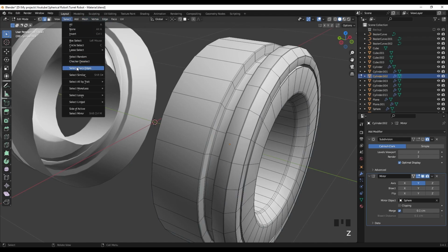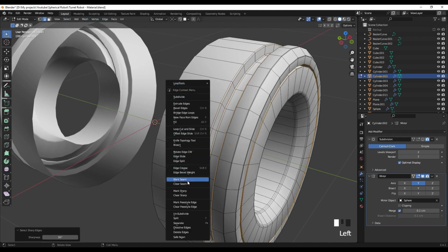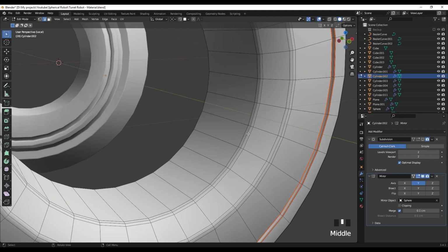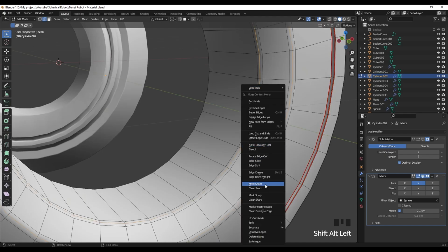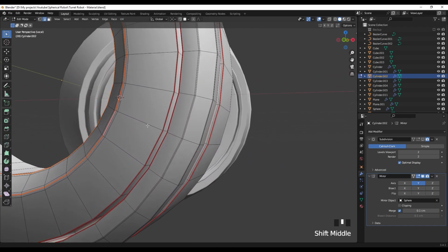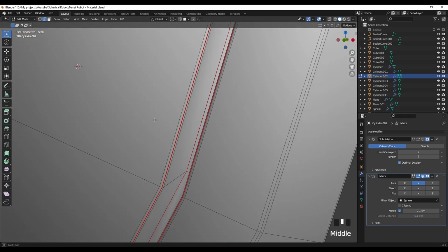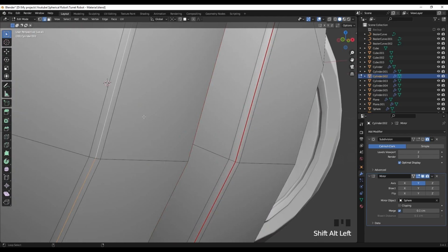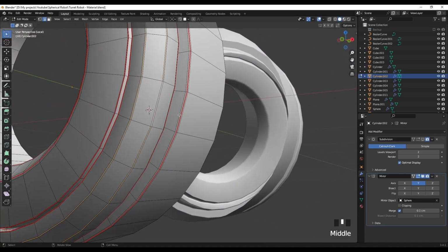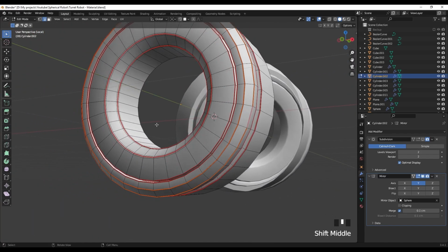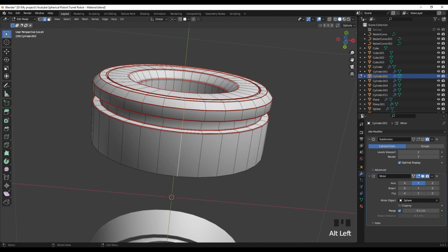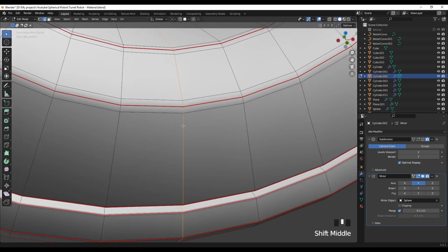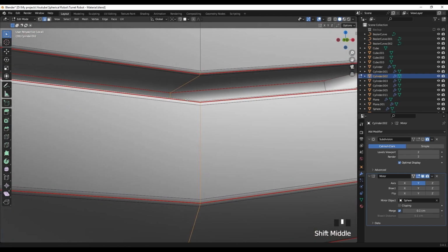view, select sharp edges, right click and mark seam, and let's see, and select these two and also this one as seam, and let's check also this one and this one, mark as seam, and we can select these loops, and also we can deselect these flat faces.